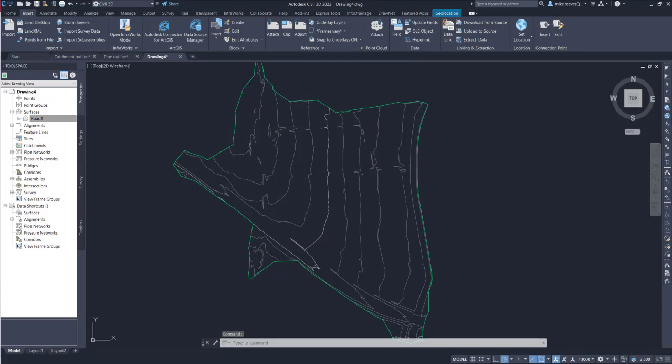Now the next thing is, as with a lot of Civil 3D work, we need to set up a catalogue. I can't claim to be an expert in either Civil 3D or particularly catalogues, but my basic understanding of it is that this is a very long list of potential attributes, and then as we create our data, and particularly as we export it and then re-import it, we need this catalogue to identify the items and give them references as we do that import and export process. So setting up a catalogue is the next task.